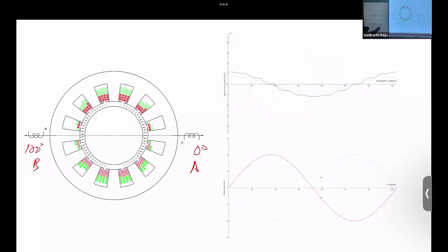So if you put a coil on the opposite side, you end up with the same standing wave in effect. This is the same as saying that I could have just put this dot here as a positive conductor going into the page, the green ones. I could have just swapped it out with a conductor coming out of the page and passed the green current in the same phase as the red current, right? The effect is the same. So it's just like putting two parallel one-phase coils.